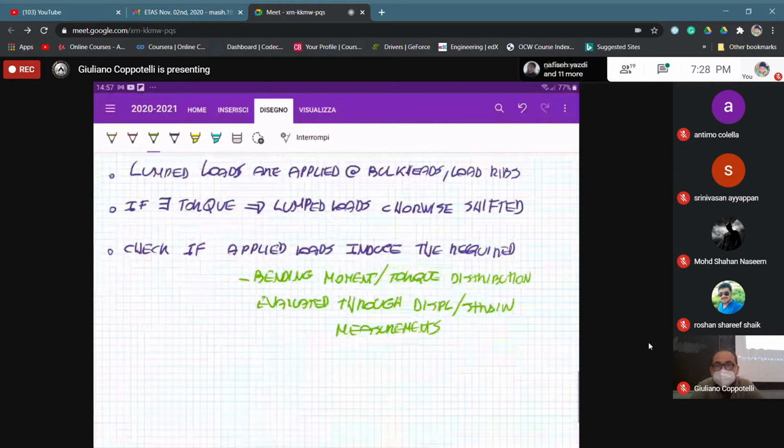However, we took part to some static tests during the years, and I can assure you that are very exciting, especially when you are at the breaking point. That you can see a lot of creaking, a lot of cracking everywhere, until there is just one boom that is the signal that everything is destroyed. But you are very happy because you finally know the maximum load, so you know the reserve strength that you got.